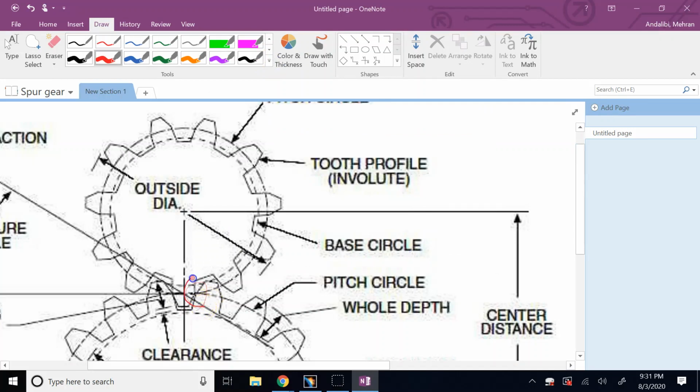So in this area, if you draw the tangent to both surfaces, it's going to look like that. And then the common normal is going to be this black line here. This line here is where the force is exchanged, because when you have contact, the normal forces are perpendicular to the common tangent. So the force that is exchanged between the two gears is along this line,